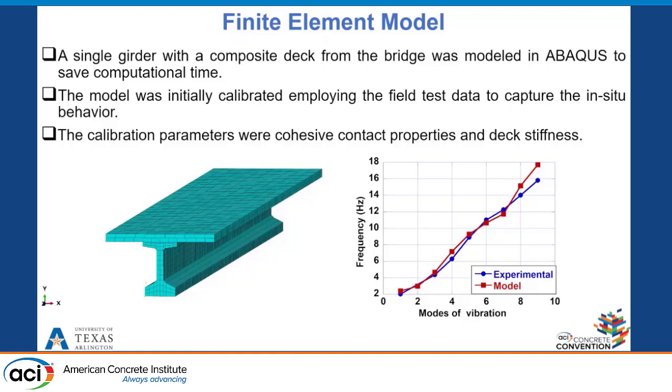The compressive and tensile behavior of the concrete damaged plasticity (CDP) model, a bilinear strain hardening model with two different slopes, was used to approximate the nonlinear stress-strain relationship of the mild steel. The stress-strain relationships of the low relaxation prestressed strands were modeled using the PCI 2021 approximation.